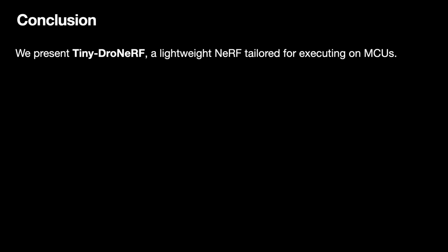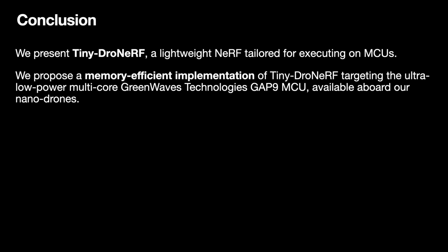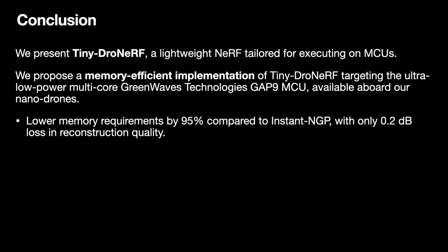We present Tiny-DroNeRF, a lightweight NeRF tailored for executing on MCUs. We propose a memory-efficient implementation of Tiny-DroNeRF targeting the ultra-low-power multi-core GreenWaves Technologies GAP9 MCU, available aboard our nano-drones. We lower memory requirements by 95% compared to Instant-NGP, with only a 0.2 decibel loss in reconstruction quality.